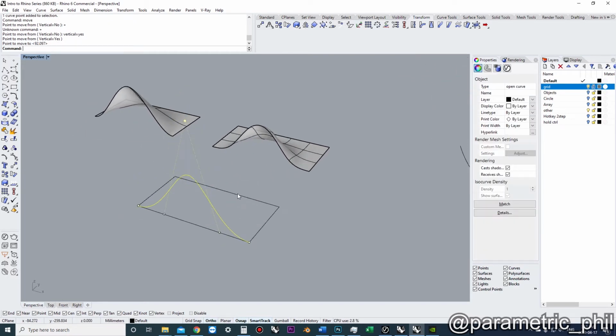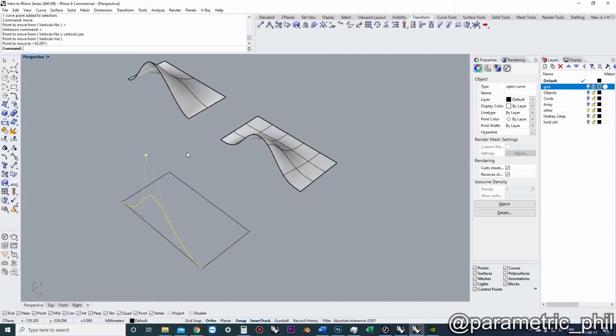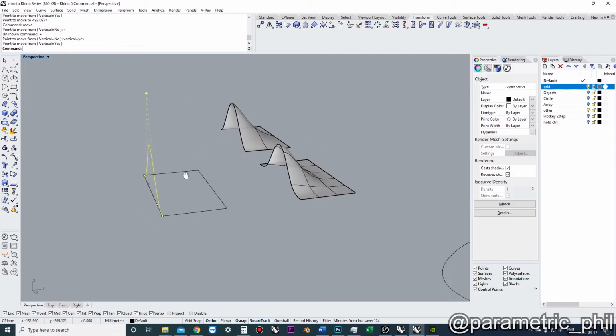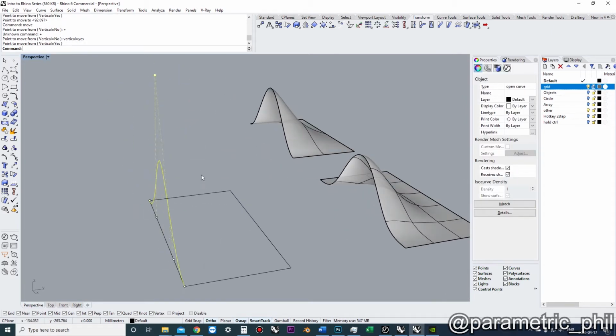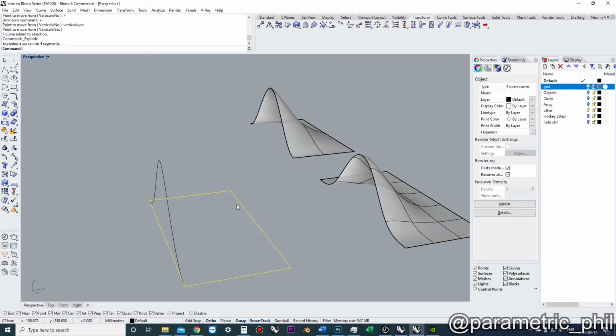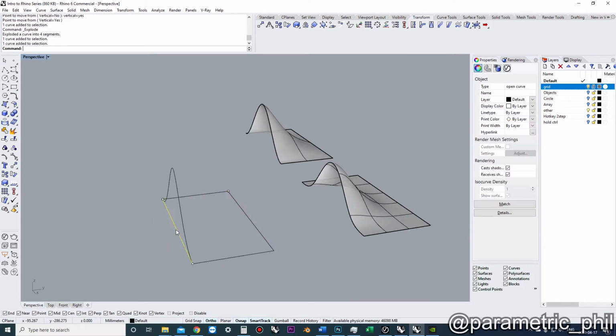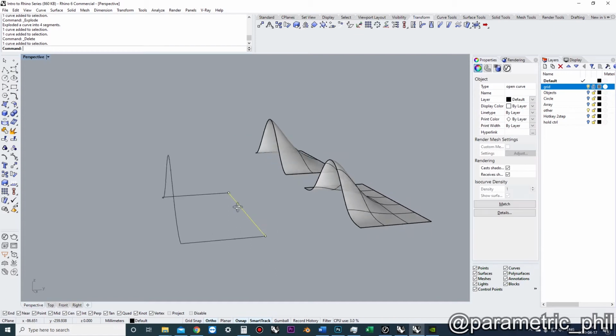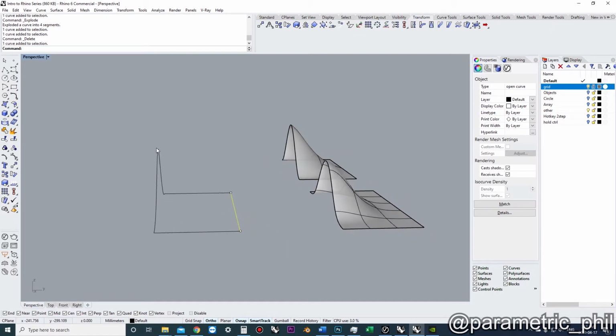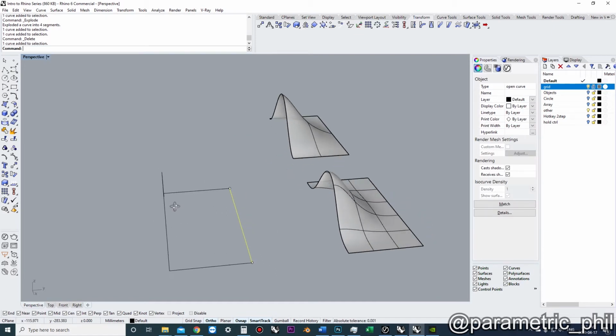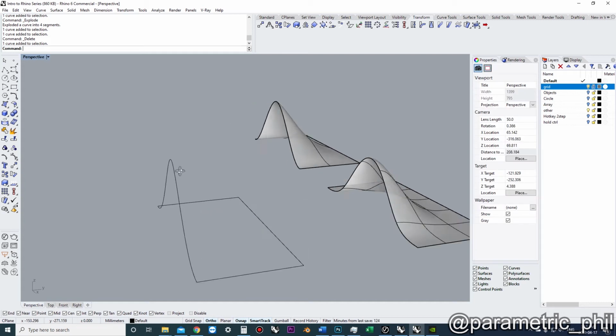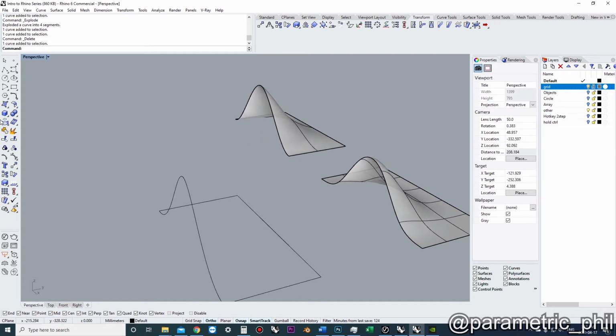And so you see what's happening. It's a very similar curve to what's happening here. I'm going to explode this, and I'm just going to delete this, and I'm going to keep this curve, but I don't want it to go straight from here to here. So I'm going to draw another control point curve just as a reference.